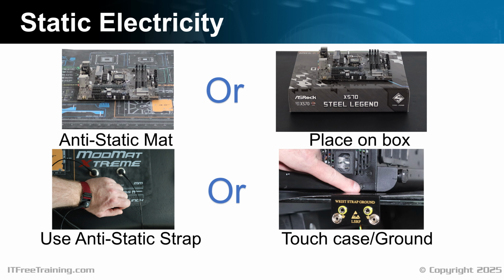After grounding yourself, you can still build up more static electricity, so don't be afraid to ground yourself again before touching any sensitive components. Now I'll start looking at how to install the CPU.